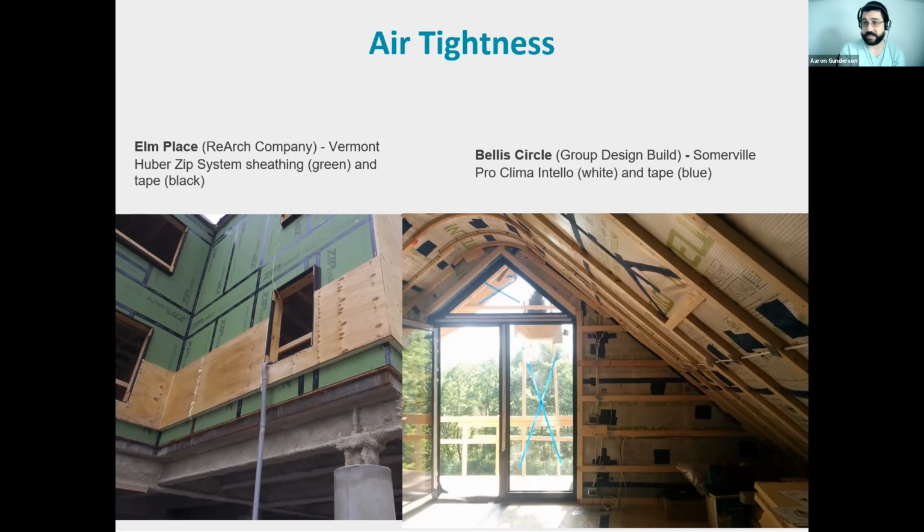This was by Group Design Build, a design build firm from Somerville. But they did an interior air barrier. So you'll see the air barrier on the outside, and you'll see it on the inside. It varies from project to project. But in this case, they did the inside. Either way, the concept is that it's continuous. That layer wraps everywhere around the project, and it's being taped everywhere. So it's completely sealed.